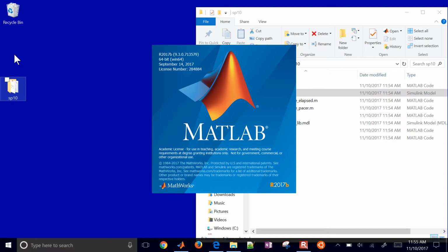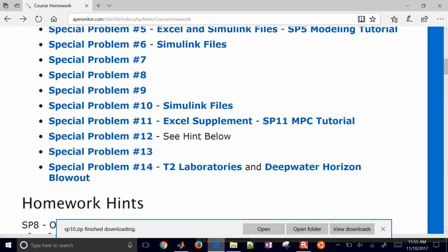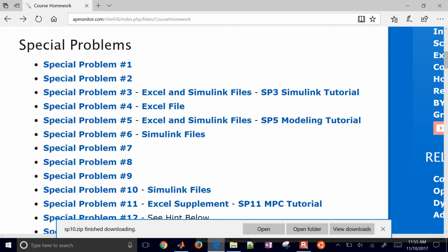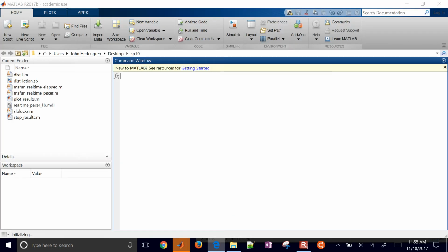The very first thing that we need to do is generate a doublet test, and so I'm going to do an up and down and then back to the nominal value for the reflux ratio. We'll start at a value of 3 and then go up and back down again. Okay, and then the other thing that we'll need as we generate this, we'll also need some Excel files to help us with our first order plus dead time fit. And I'll just grab this one right here.